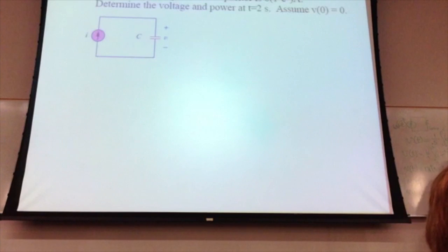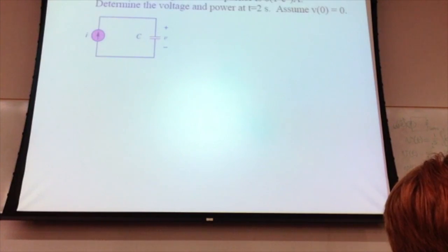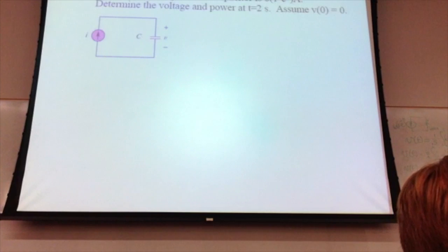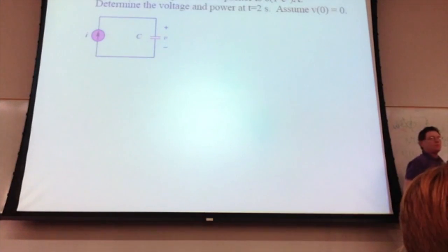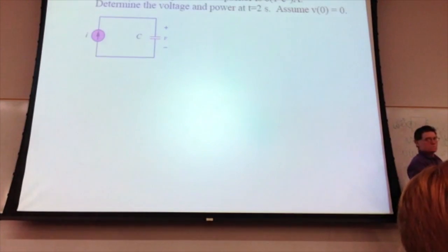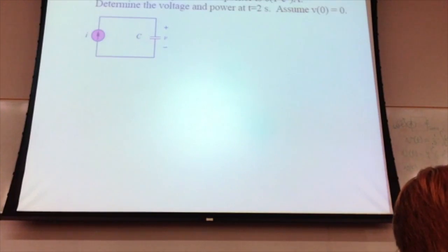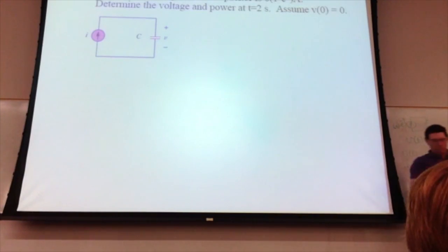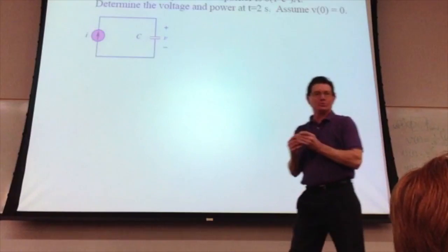5.19. All right, and to get the power at t equals 2, p at t equals 2, that's equal to v at 2 times I at 2, which is equal to 13.62 times 5.19. Multiply those two numbers together. 70.69, and that's watts, because power is measured in watts, not in dilithium crystals.